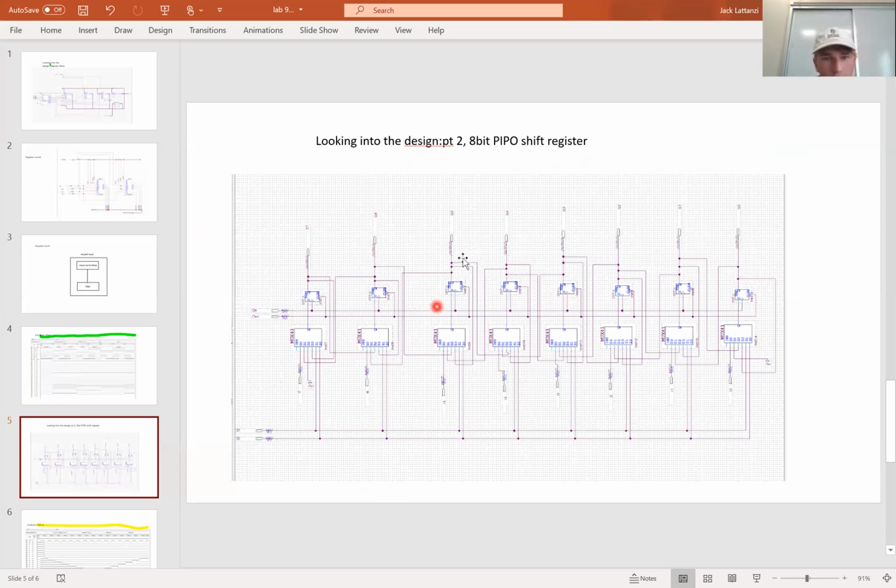The way this circuit works is there's a common clock pulse and a common clear pulse to all of these to create movement in the circuit, as well as a common function selector of S1 and S0. The way S1 and S0 work is if it's set to 0, 0, then you can see that the multiplexer allows this one to flow, which is on D0 for every single one of these, and that is the input. So that sets the inputs in.